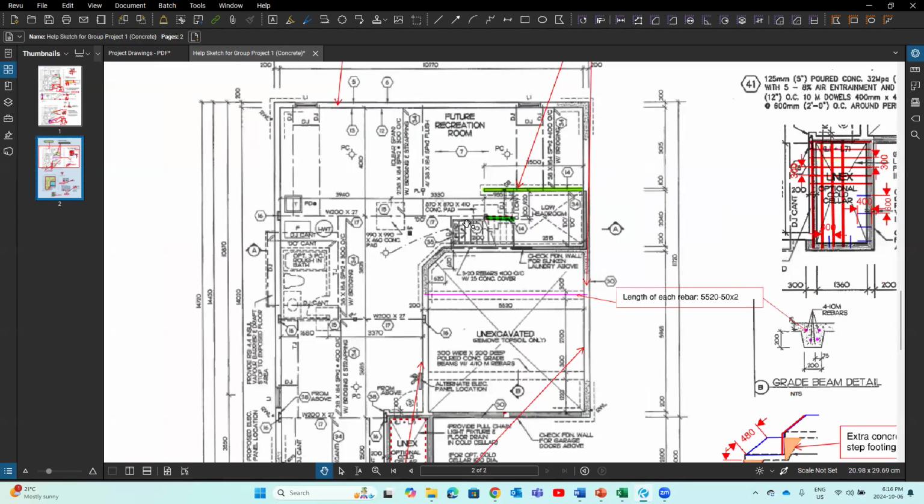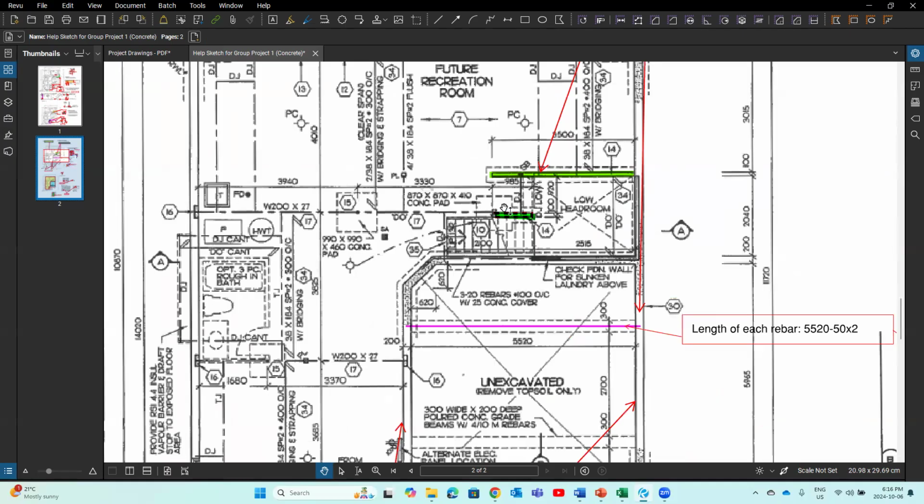And also if the foundation wall has an open end like this, every open end we also add one extra anchor bolt. For example, this piece of the wood framing wall, right? The length is only 985. We still need two anchor bolts. Think about the spacing is 2400, 2.4 meters.